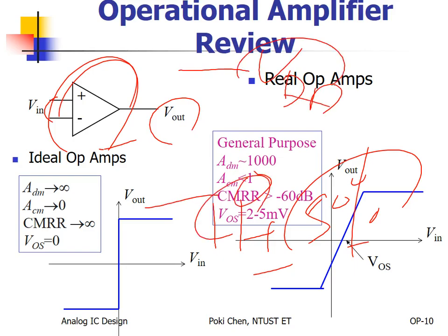That's it. I promise you, if you go to our library, our warehouse on the first floor, you borrow as many op-amps as possible, apply VDD and VSS or ground, then short the input. I promise you, only 2 possibilities for such open loop applications of op-amp. The output will be either positive saturated or negative saturated.